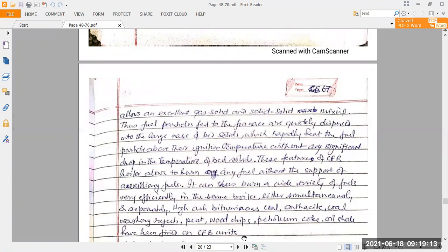So not only fuel with a really small amount of ash, we can also use high ash bituminous coal here. After burning, it gives a considerable amount of ash, which means it does not leave a sufficient quantity of combustible material for burning in the furnace itself.